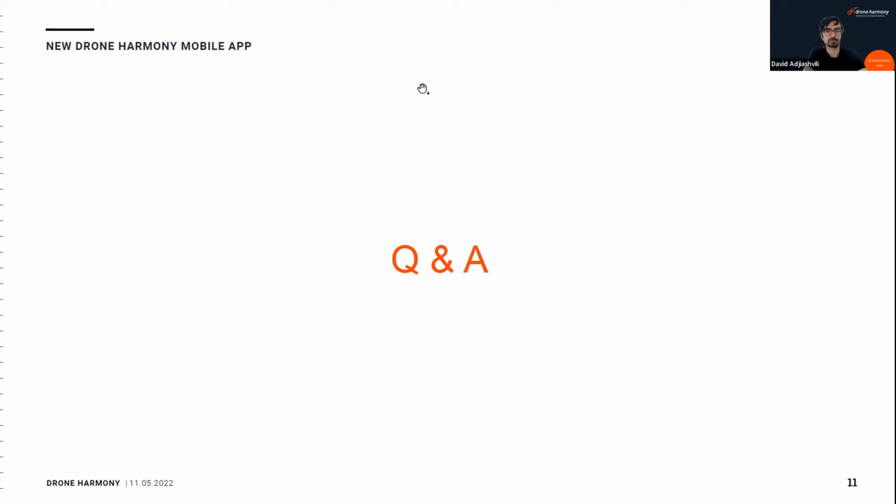The next question is, which easily packable drone do you recommend for building photogrammetry, one that can easily be carried on an airplane? From our experience, the answer depends a little bit on the type of resolution you want to achieve for the building inspections. It's definitely advised to fly something with a good sensor, something from, let's say, Phantom 4 level upward.